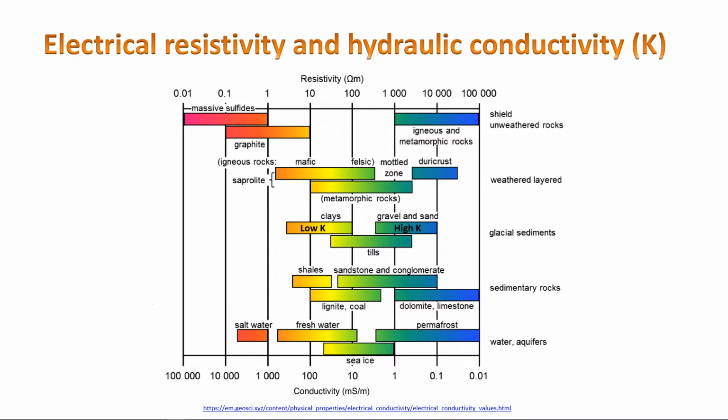Say you take an image of the subsurface, let's say we are at Immokalee, and there we are expecting to find mainly sand and gravel and maybe some clay layers. So you do your resistivity test, and you will find areas with low resistivity and areas with high resistivity.